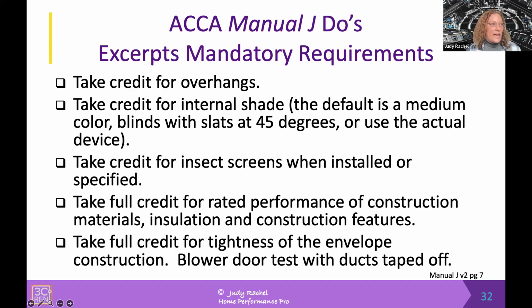And the only way to do that is doing a blower door test. That's typically easy enough with an existing building, and it's downright impossible with new construction. So with new construction, we need to talk to the contractor and find out, do you have any sense of how tight your buildings typically are? Is there any goal set up for this building of a tightness number? Is it an ACH? That's fine. I can deal with ACH. I can deal with CFM, but we need to find out how exactly loose or tight, leaky or tight that building is going to be.